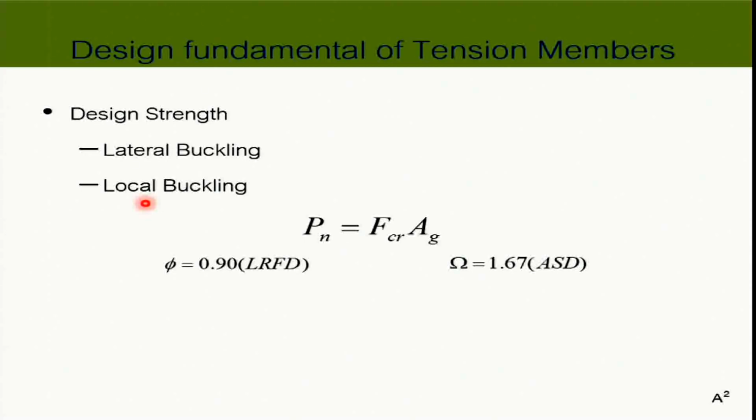And because we start utilizing the shape and edge, for example, the problem with utilizing the shape is that if you create the flange to be too thin or the web to be too slender, it may have its local failure. So the flange may fail, the web may fail before the member fails. So that is the idea of local buckling.